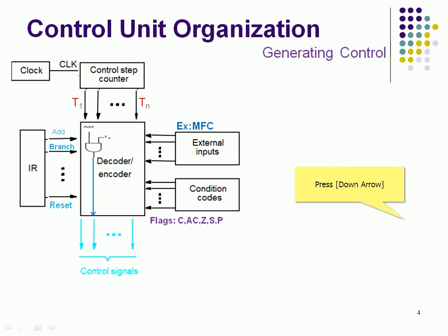We can see one example here, generating the control signal for Z-in, right? You know that Z-in is involved in most instructions, even in instruction fetching or the execution phase, where we have seen the register transfer, and also the simple example add R3 in brackets, comma R1.